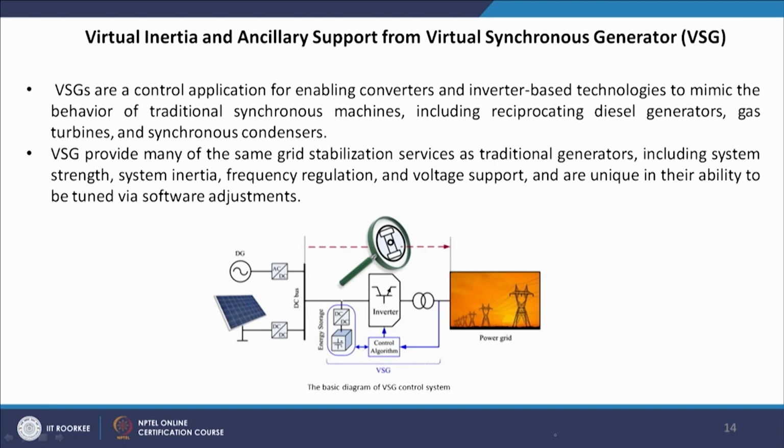Now, virtual synchronous generator VSGs provide many of the same grid stabilization services as traditional generators, including system strength, system inertia, frequency regulation as well as voltage support, and are unique in their ability to be tuned via software adjustments.